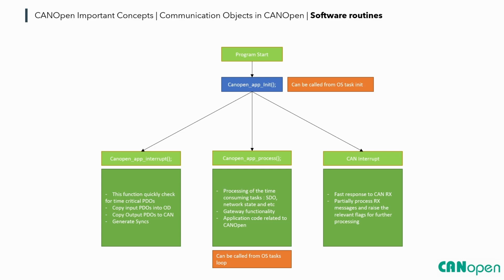Okay, so now let's talk about CANOpenNode. CANOpenNode is an implementation of CANOpen, a software written in C, and it's available on Linux, PIC microcontrollers, and also STM32. In STM32, we have this architecture. Basically, it's not just STM32, but all of the ports that we have for the CANOpen stack.